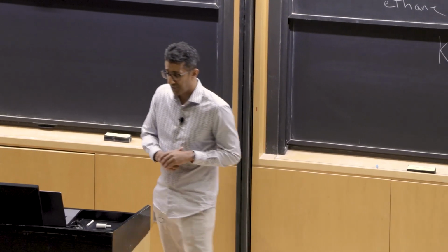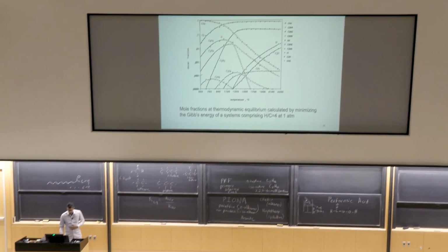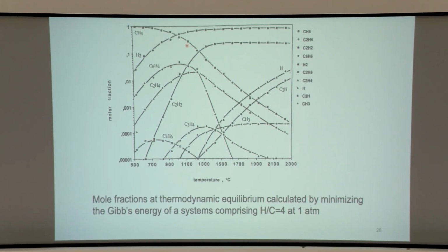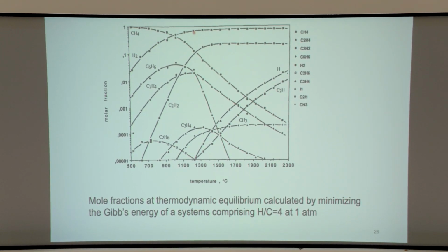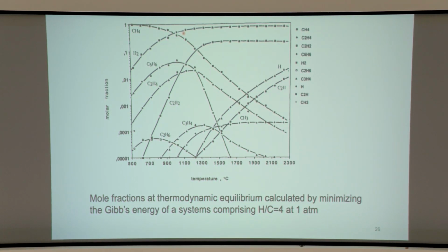This graph tells us right away, in order to do this reaction, to get enough hydrogen, I got to be at a pretty high temperature, yeah? Even forgetting about the kinetics, just by thermodynamics, if I want to start to form more hydrogen than methane, I got to come to above something like 1100 degrees Celsius. At the same time, though, I'm going to be making benzene and acetylene. I might want to minimize the formation of benzene, so then I heat up my reactor even further to, say, 1500 degrees Celsius. I'll get more hydrogen, but now I'm going to get also a lot of acetylene.